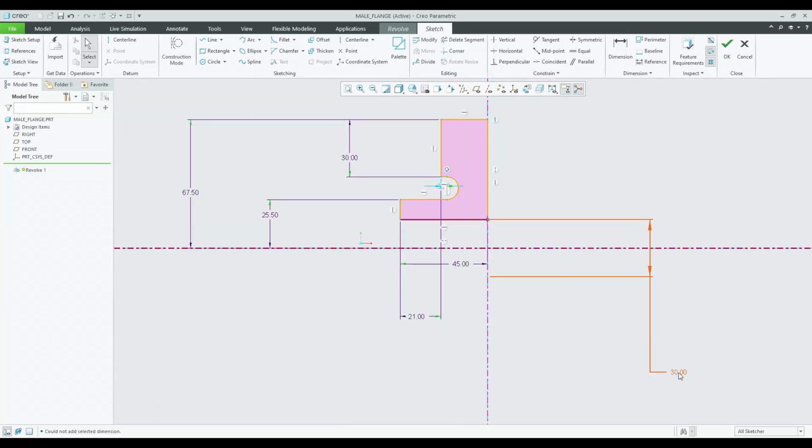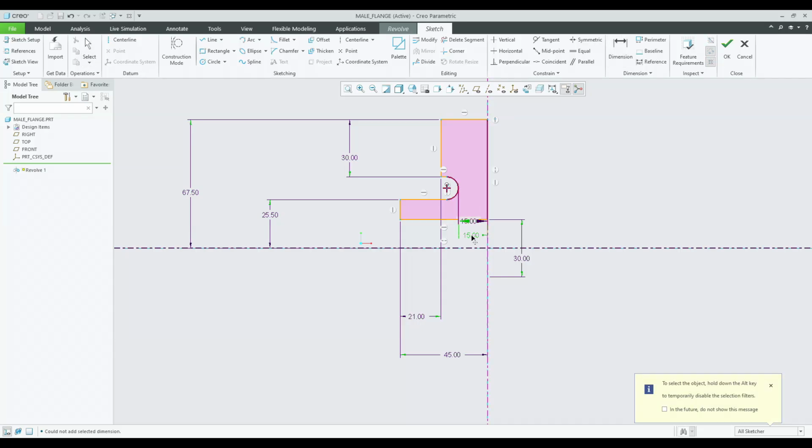So here we can see the diameter of the internal hole is equal to the shaft diameter, which is D. The total distance is equal to 1.5 into D, or else we can make it from here to this distance will be like, sorry, here to this distance will be like 0.5 into D. The remaining distance is 0.7 into D and the total distance is 1.5 into D.